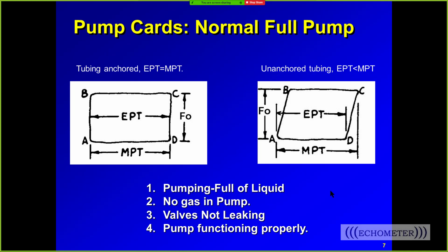and the paraffin starts to apply mechanical friction to the rods. So the pump card is concave outward above the FO max line if the pump intake pressure is zero, and the pump card is concave outward below zero on the downstroke. So that's the pump card. It can look kind of like a balloon on the top and the bottom of the pump card, curving outward. Yeah, a lot of friction.